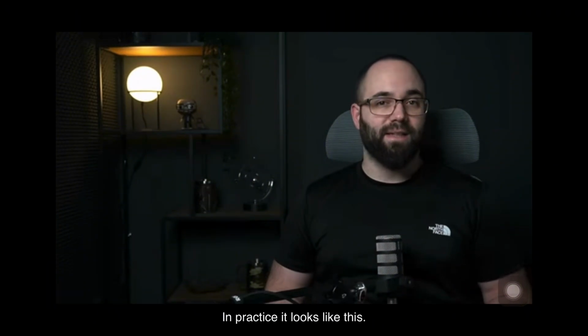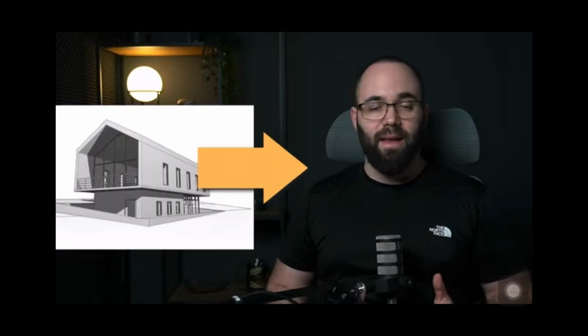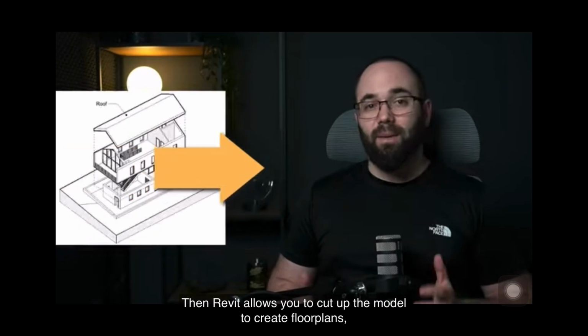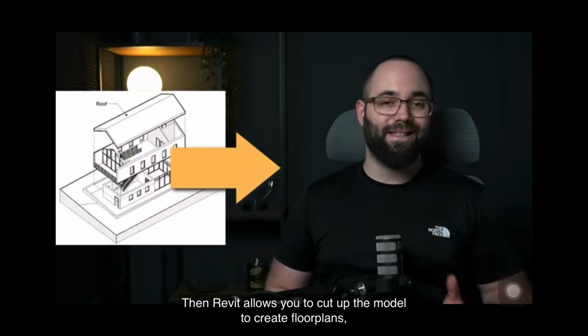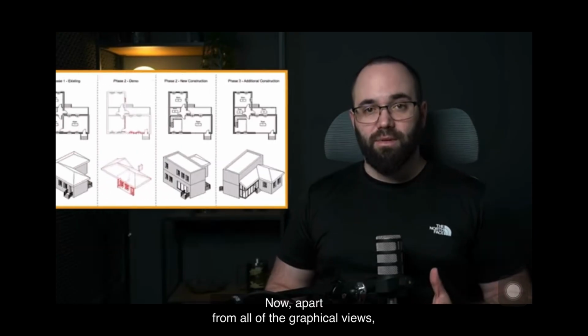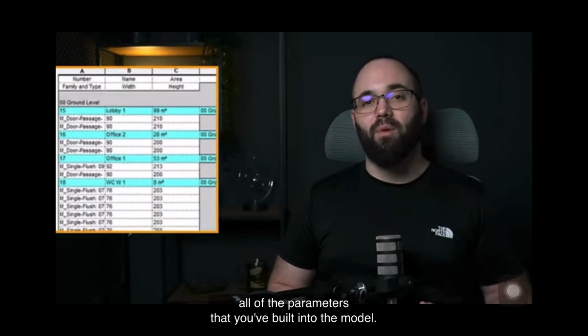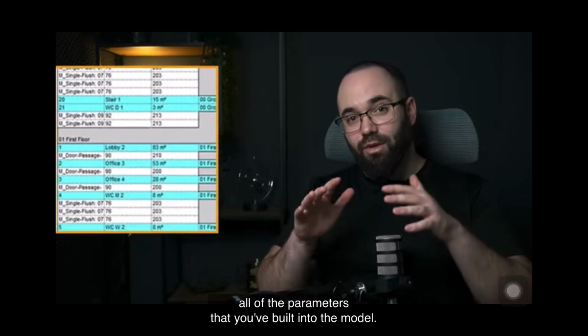In practice, it looks like this. You have your building tools that you use to build the model. Then Revit allows you to cut up the model to create floor plans, sections, callouts, elevations, camera views, and more. Now, apart from all of the graphical views, you can create material takeoffs and schedules that use all of the parameters that you've built into the model.